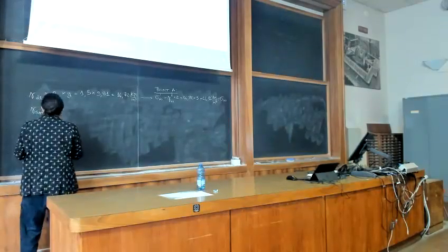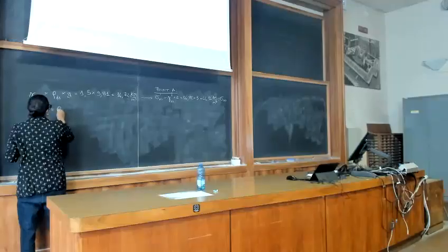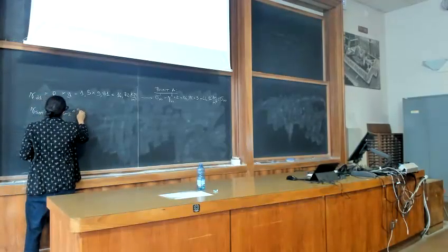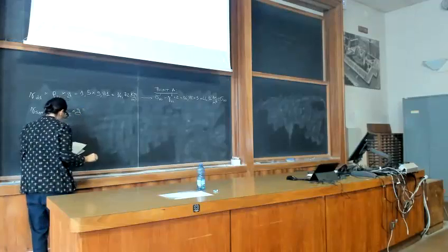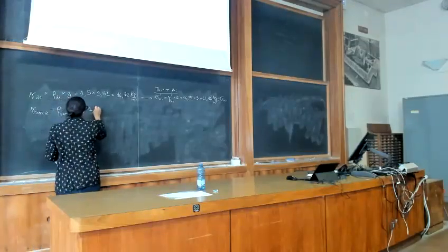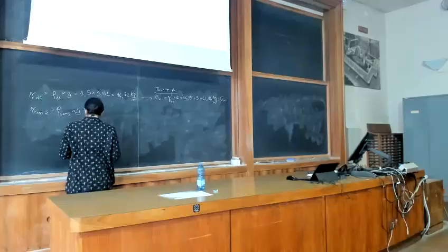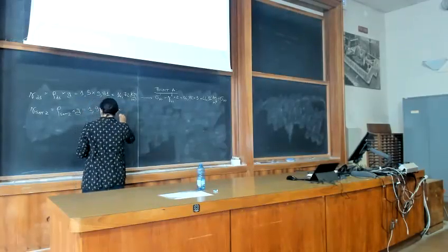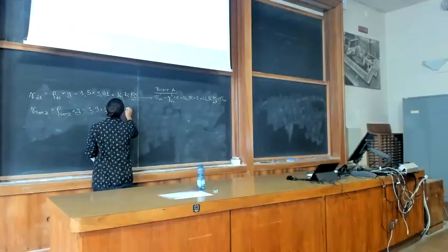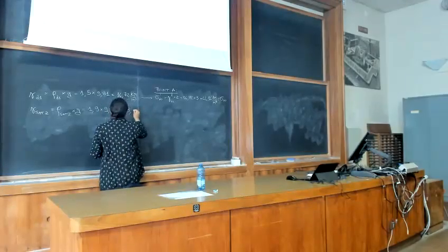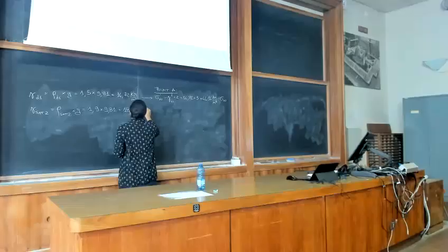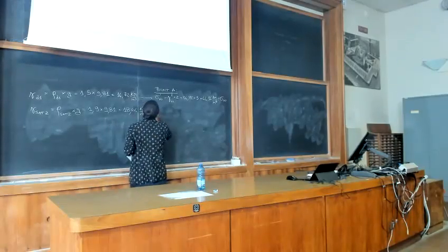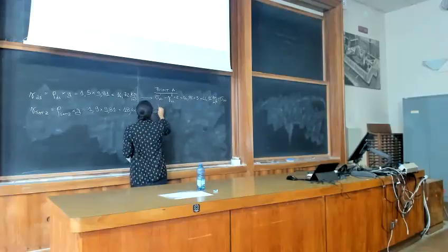The saturated unit weight in this case is rho sat of layer 2 multiplying g. So you have 1.9 multiplying 9.81, and you obtain 18.64 kilonewton per cubic meter.